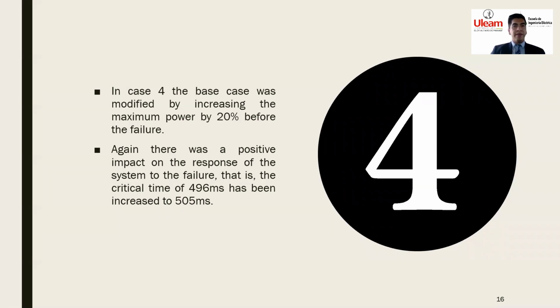In case 4, the base case was modified by increasing the maximum power by 20% before the failure. Again, there was a positive impact on the response of the system to the failure. That is, the critical time of 496 milliseconds has been increased to 505 milliseconds.